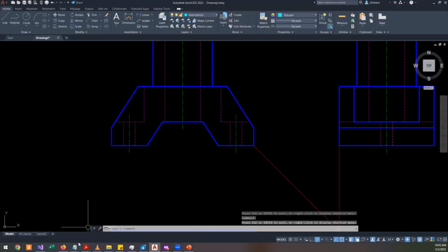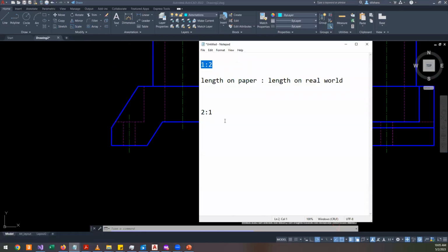Okay, let's get started. So you know why the scale is important. First identify the suitable scale that you're going to print the document. Once you identify that, it will be a smooth ride. But you need to use this scale every time you add the dimension, text, or multi-leader. Actually, you format the drawing and then use that style.